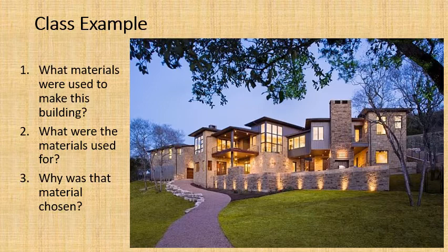What about these walls here? They're made from wood. Why are they not made from concrete? Well, look at this design here. This is actually flexing in this direction. Now, concrete has really good compressive strength. That means you can squeeze it and it can withstand a really big force. But equally, concrete is very weak in tensile strength and flexural strength.